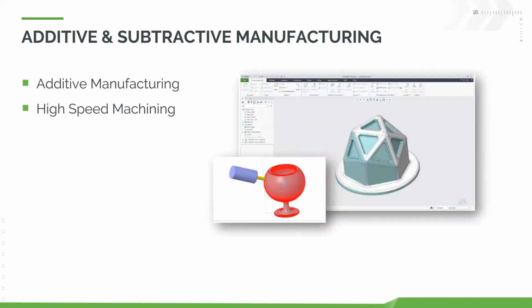Several different improvements in high-speed machining, better surface finish and flexibility with the new geodesic 5-axis finishing toolpath. This is something that I'll show what looks like in the context of Creo. Really helps to improve things like tool life, avoids chatter, faster overall machining, and much faster overall NC programming time as well. From there, we also have fully associative in-process stock models in the model tree. So you can turn those off or on. They're fully associative at any time. So those can be easily updated.